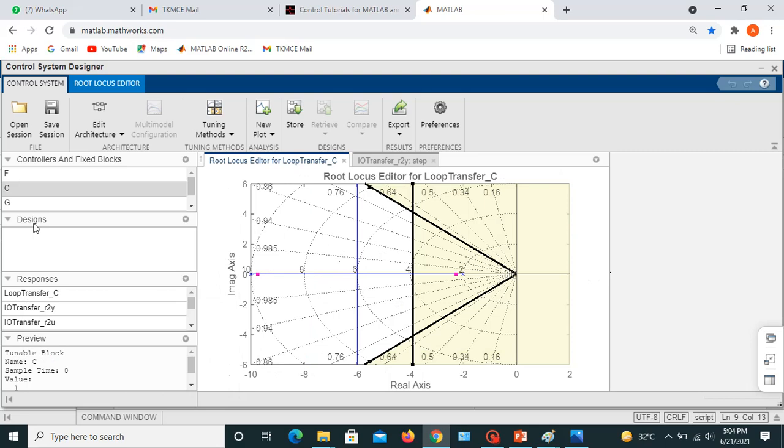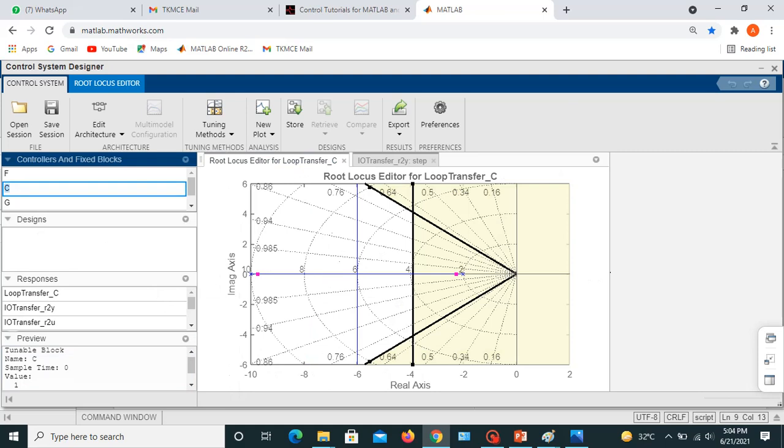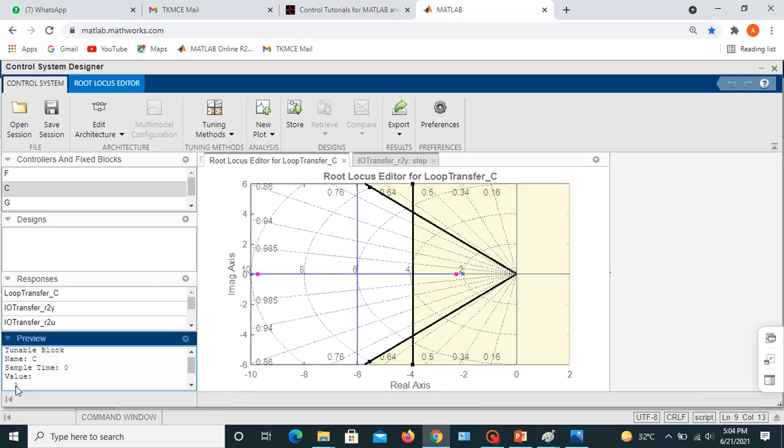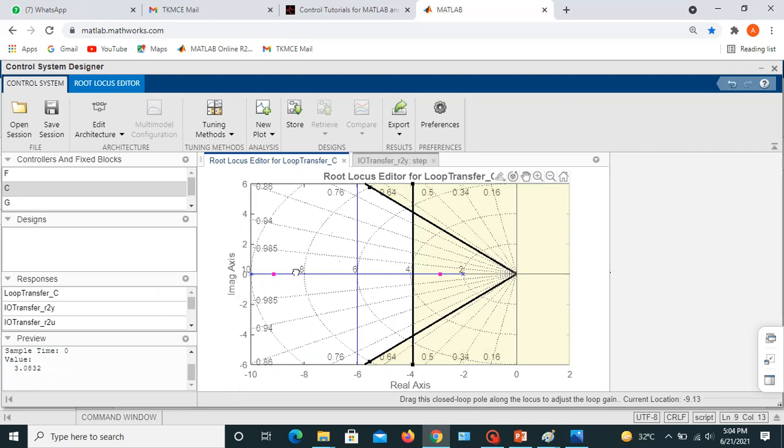The two rays centered at the origin represent the overshoot requirement. The smaller the angle these rays make with the negative real axis, the less overshoot is allowed. The value highlighted is the corresponding loop gain. The vertical line at s equal to -4 represents the settling time requirement, where the farther to the left the closed loop poles are located, the smaller the settling time is.